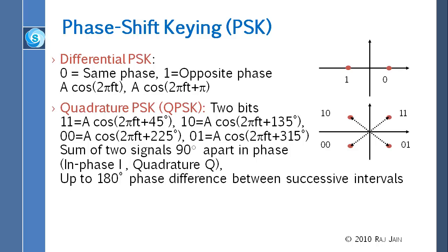It has amplitude, phase, and frequency. Right? So we selected a coding, and people have tried all kinds of things. One person selected the coding where 0 is represented by a sine wave and 1 is represented by the same sine wave but with 180 degree phase. So we just have to measure the phase of the signal.